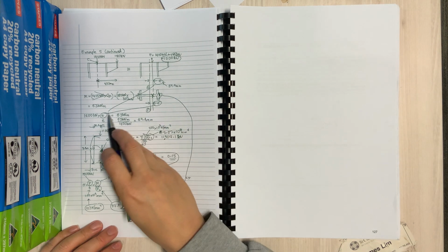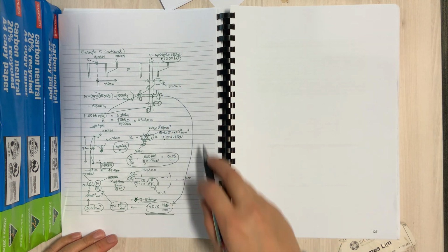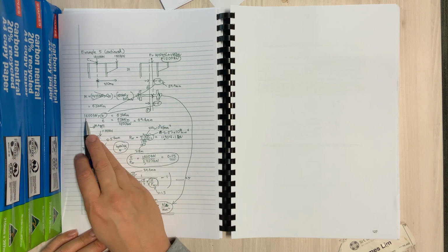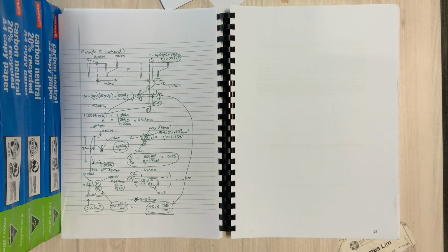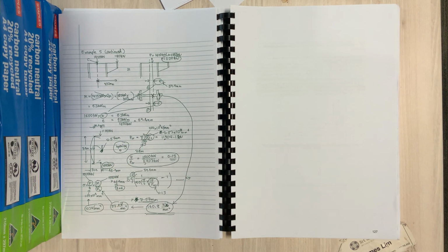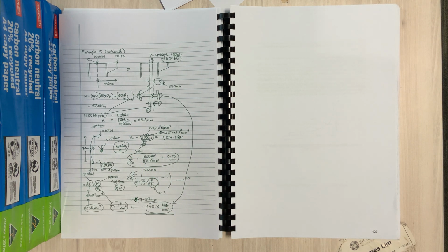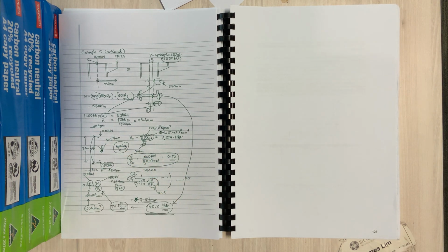So now we've got the eccentricity, which we see there, and we need to work it out. So the eccentricity e is that moment, equal to 63 kilonewton meters, and then you divide that by the 1600, and you get 39.4 millimeters. Right here, I've drawn what the deflection might be, with the load being applied at the end here.